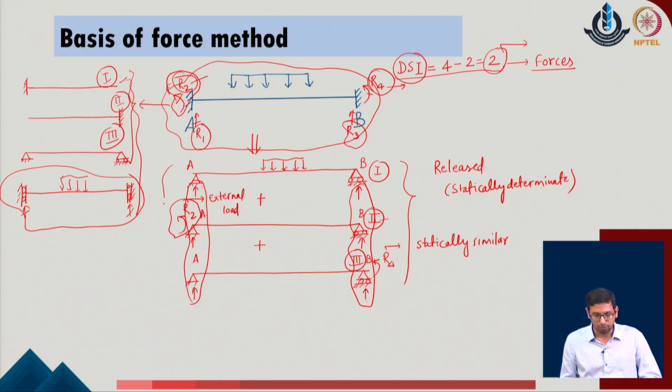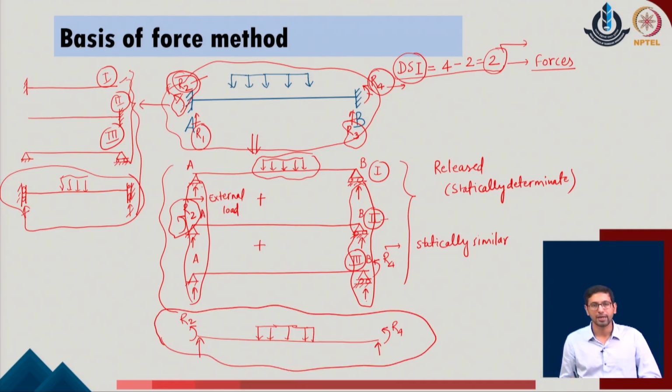That means once someone adds these three systems together, one gets some value of the reactions in the vertical direction at the two supports, and the two unknown reactions R2 and R4 at the ends of the given system. The original system's load, which is provided in system 1, is also included, and this system is the same as the originally defined problem, at least in the static manner. That means in terms of the forces, this system and the original system are the same, and the original given problem has been reduced into these three problems defined for the statically determinate system.